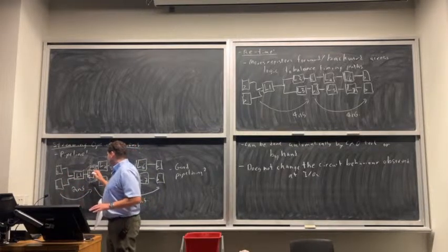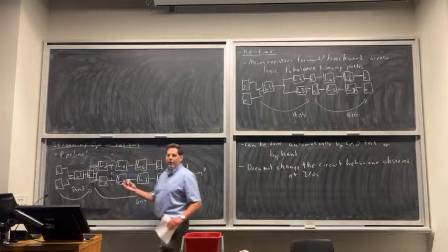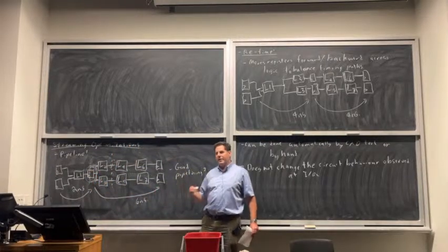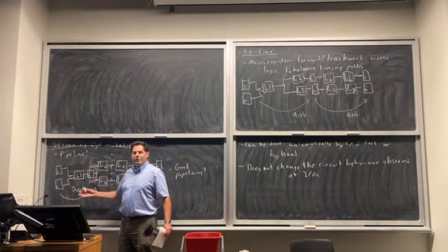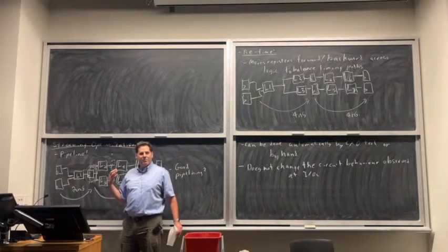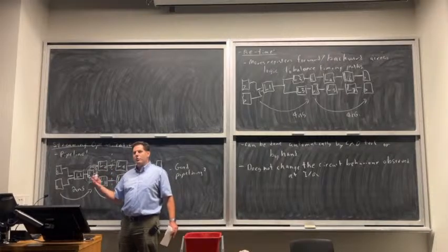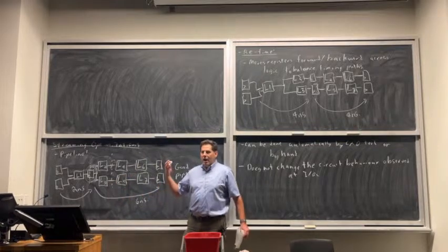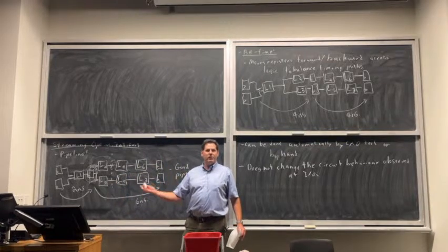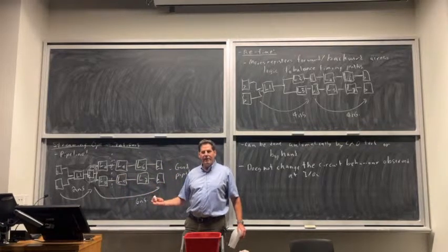If you put this in the chip and things are going wrong, there are tools that the FPGA vendors have where you can actually basically observe the registers and bring data out from the running system. Okay? And sometimes you have to use those tools to actually debug the hardware because you're getting unusual cases that you missed when you were simulating the design that are showing up as bugs in the hardware.